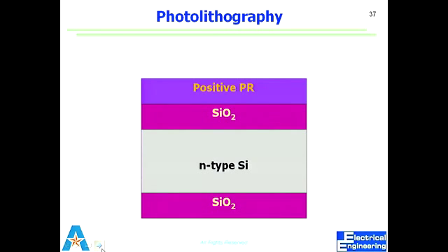While it flies off, it's going to result in a thin uniform layer on the surface. We make a big puddle of that resist and essentially cover the whole wafer with that puddle of resist material. It's liquid. So once I spin it at 4,000 RPM for 40 seconds, the thing just flies off and leaves behind a very thin layer of resist.